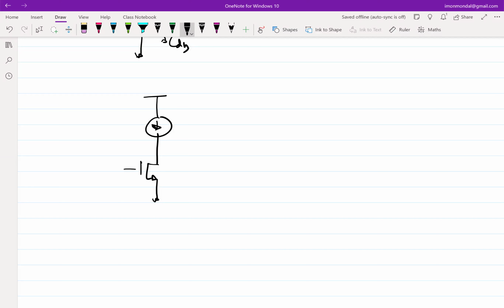Cox essentially. Cox is epsilon ox by Tox, right? So Tox is thicker. You can think of it this way: the unit change of IDS for every delta V in VGS basically boils down to gm. So for every delta V change in VGS, how much delta you get in your current for the same W by L is proportional to Cox, right?